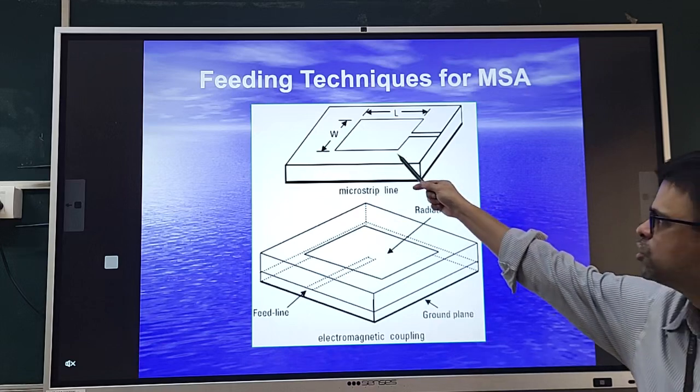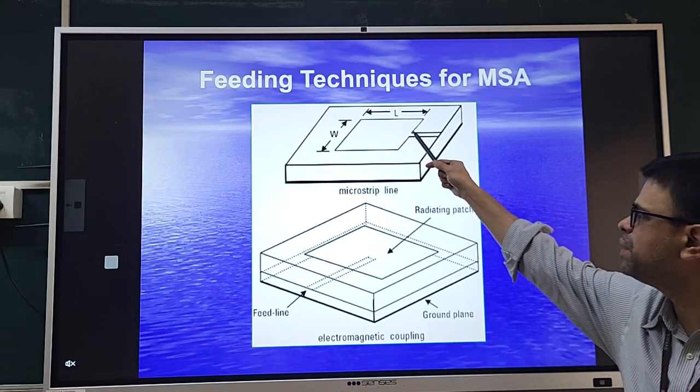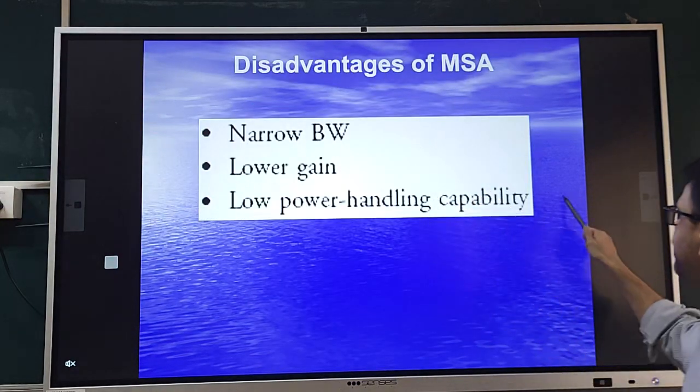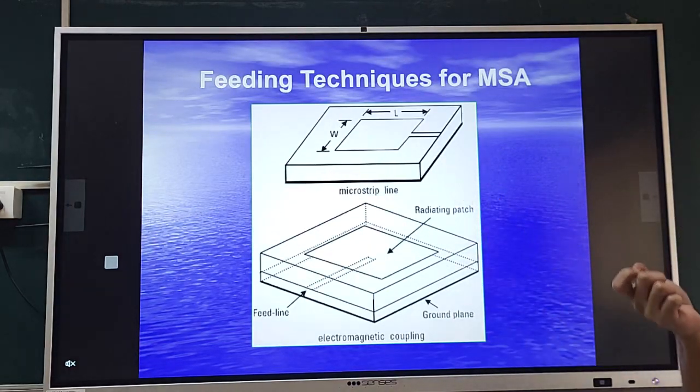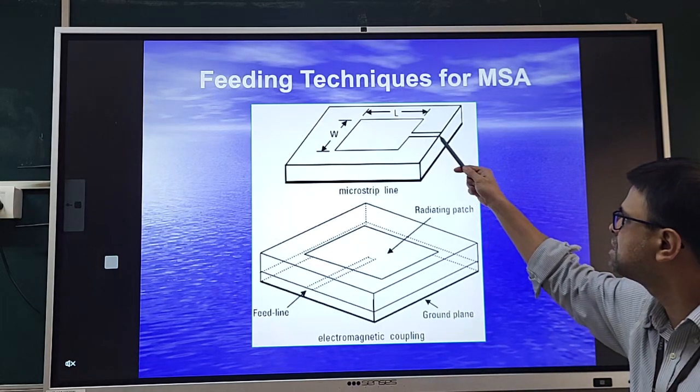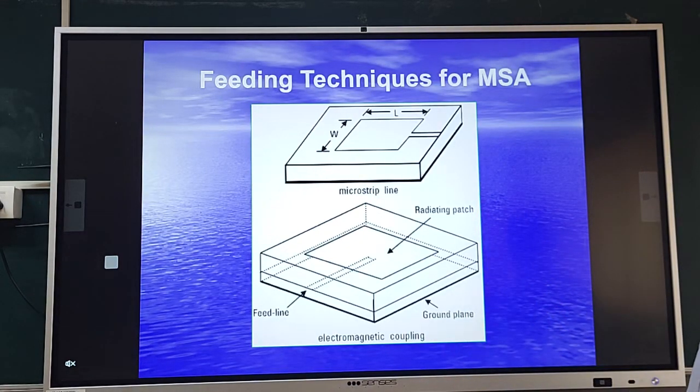Okay. So again, you need to appropriately calculate the edge impedance at that point of the microstrip antenna, then design the characteristic impedance of this line and do the matching. When we later on go to the rectangular microstrip antenna case, I will touch upon more of these design aspects.